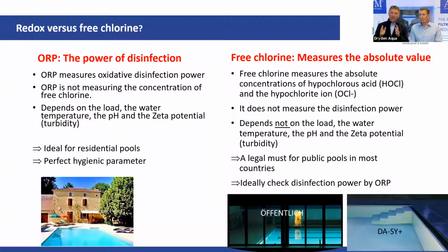It works, but you have to work with gold probes. And if you go on a very low salinity, I mean 500 milligrams per liter or 600 milligrams per liter, then ORP starts to play crazy.